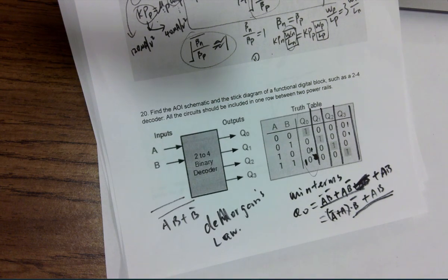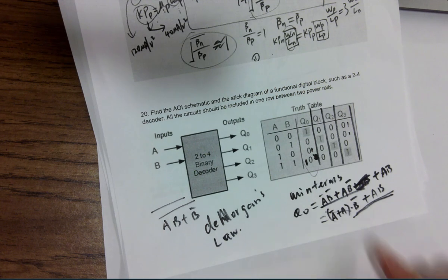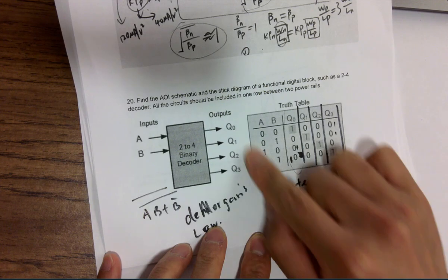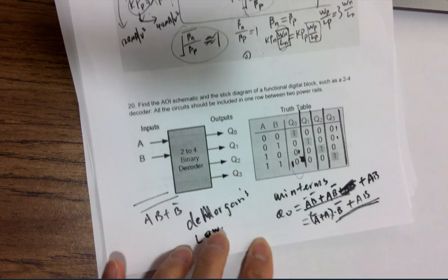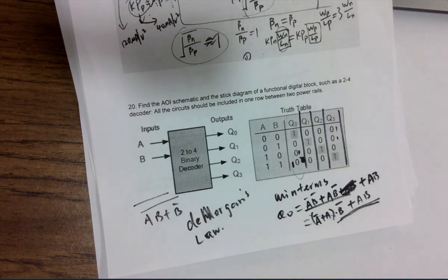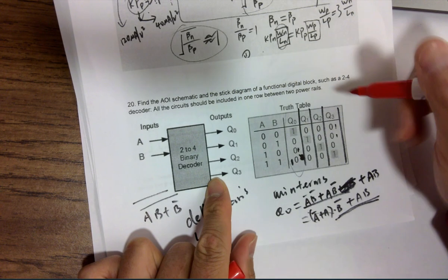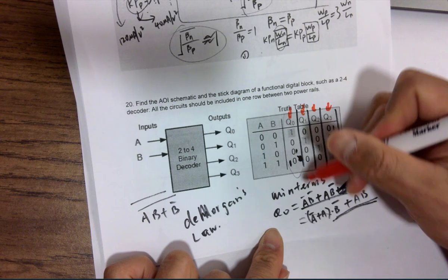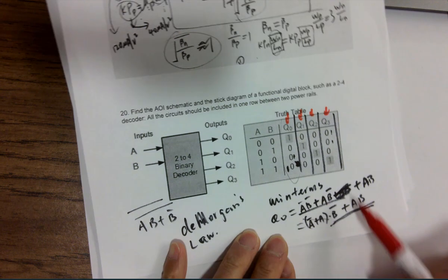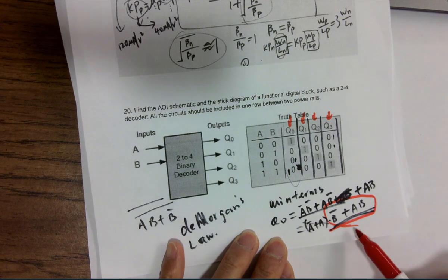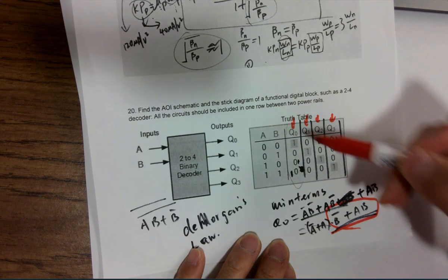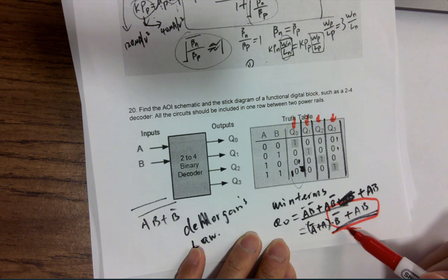Okay. I don't really understand how you got the minterms in the first place. Yeah. So this is something you have to study, right? So it's from the logic class 2 years ago you took, right? So you have a truth table, you have 4 outputs, you need to deal with each output each time, right? Because each output has one certain digital circuit. Since each output gives you one logic expression, and you are converting that logic expression into a digital circuit, so every one needs a certain digital circuit.